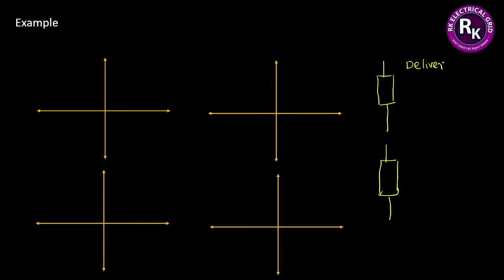First thing, power, it is only delivery. There will be no absorption. But there are some elements that will absorb the power first and then deliver or dissipate. You know who will dissipate and who will deliver the power. If it is the resistor, it will dissipate instantaneously. If it is the inductor or capacitor, first it will absorb, and in the second stage it will deliver the power to someone. Okay, sir. How do I identify these two things graphically?